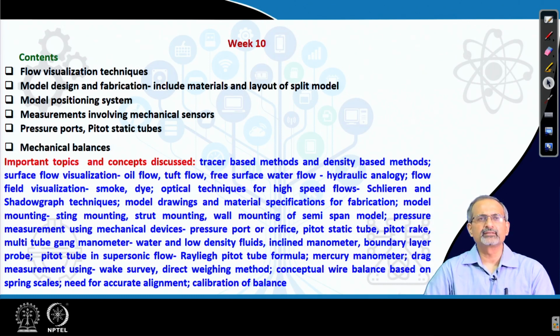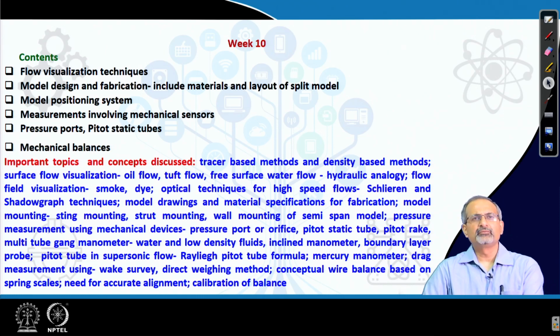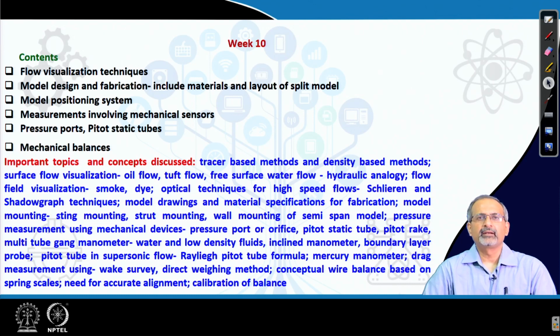Flow field visualization using smoke and dye was discussed in the context of low speed flows, while optical techniques were discussed for high speed flows like Schlieren and shadowgraph techniques. Then we discussed how to prepare model drawings and material specifications for fabrication purposes so that you can actually move on to some practical work in wind tunnel testing.